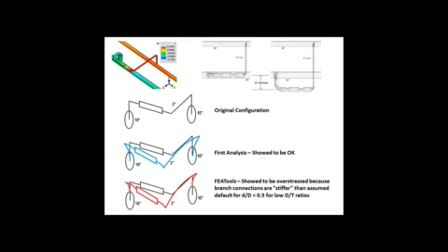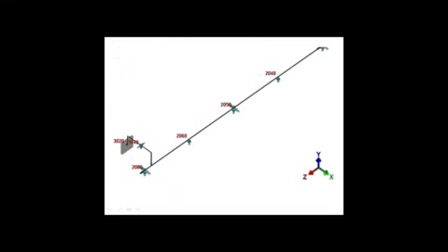For this particular configuration, everything was very stiff. So that little bit of extra flexibility on both sides of the line added enough bending so that we weren't overstressed. When we ran FEA Tools, it says that's not what really happens. FEA Tools builds what we see with the red piping system, so it puts rigid elements from the center line out to the surface for everything, because that's the way the systems really behave structurally. So in this case, we put a lot more bending back on the elbows, and the elbows were overstressed. And we need a little bit more flexibility. So in this case, FEA Tools showed us where we weren't conservative with these small branch connections.